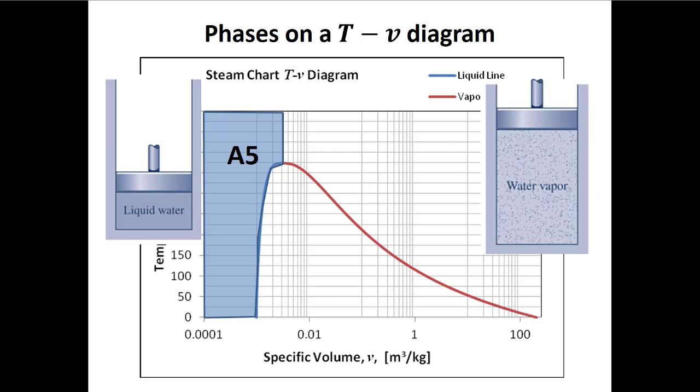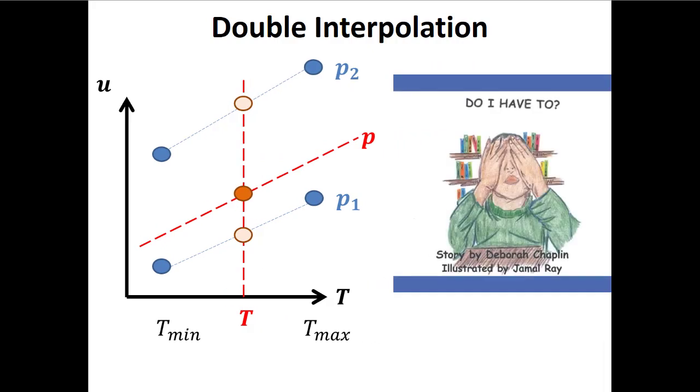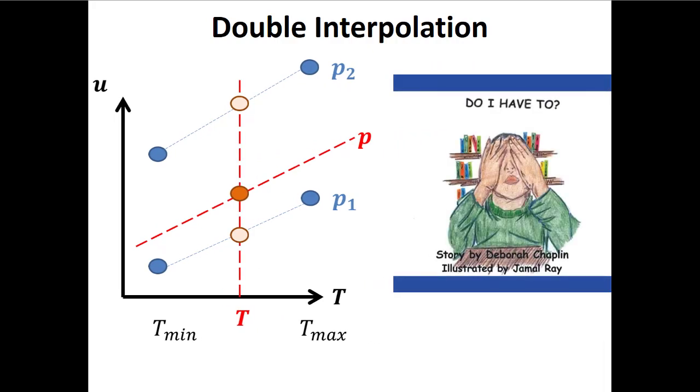It gets a little trickier, like we've said, when we're looking at these subcooled liquids, because here the data is pretty sparse. There's not a lot of subtables when we're talking about subcooled liquids. So we'd have to go through a lot of effort to make our own subtable at the right pressure. Maybe we'd have to do some kind of double interpolation where we interpolate both with pressure and with temperature. And I think for most of us, we'd prefer not to do this.